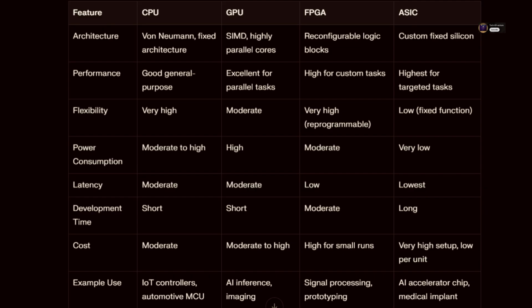Right. Different need. I'm designing high reliability automotive radar. Or maybe critical telecom infrastructure like a 5G base station component. I need guaranteed sub-millisecond response times. Latency must be absolutely predictable. That's the deterministic latency requirement we talked about. That points squarely at the FPGA. Precisely. Real-time, low deterministic latency is the FPGA's sweet spot.